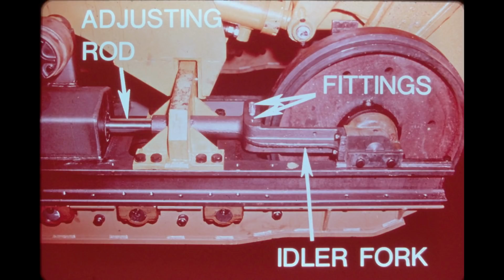In other units, the shaft of the idler fork serves as the cylinder for the adjusting mechanism. A piston is installed in the shaft, and an adjusting rod is positioned between the piston and recoil spring. The two fittings on the top of the fork are readily accessible for adjusting track tension.